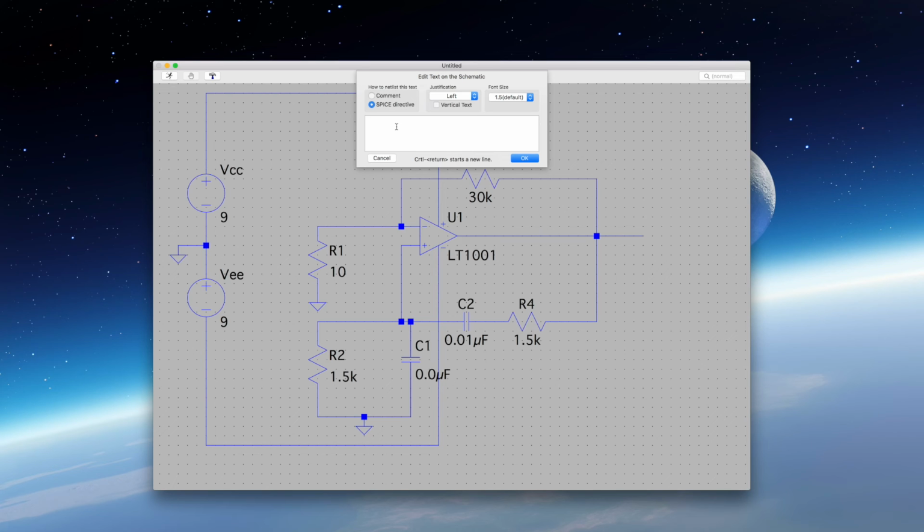And this one here will be the transient analysis, so dot tran, okay? And then specify the amount of time. So maybe 0.01. Let's see what happens, okay? I might have to go to 0.01. We'll see. We can play with that.